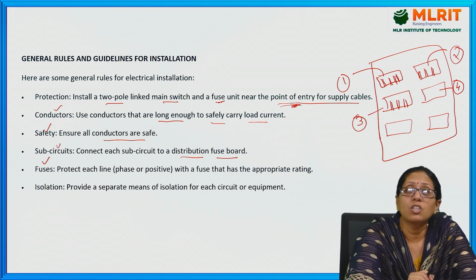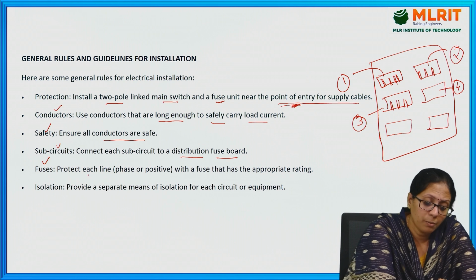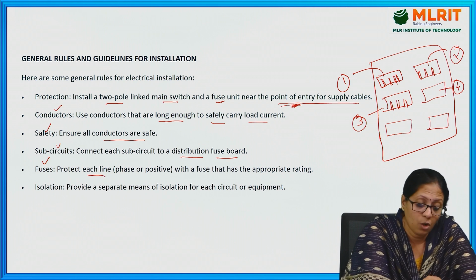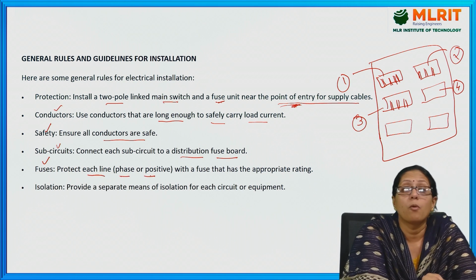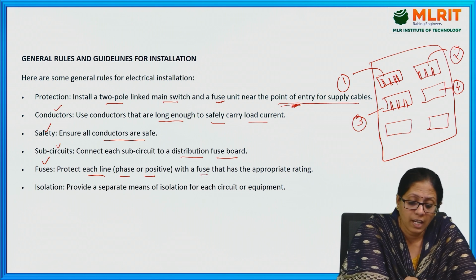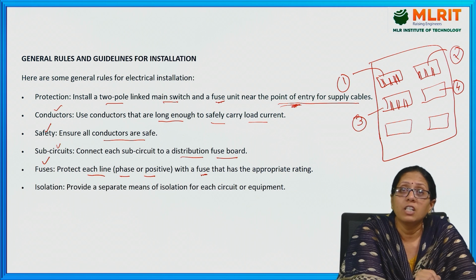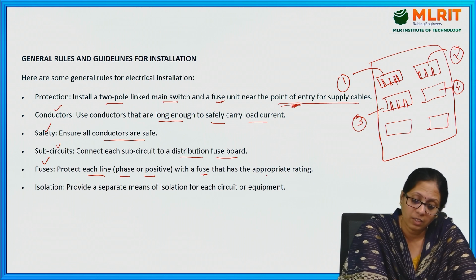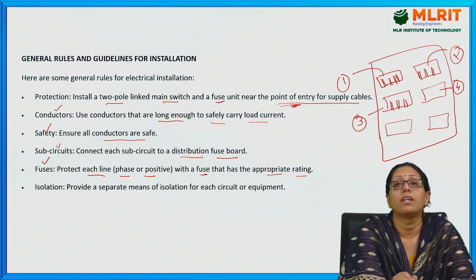The next one is fuses. Protect each line, which is phase or positive, with a fuse. For each line, a fuse should be connected that has the appropriate rating.